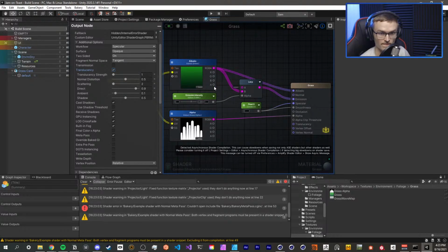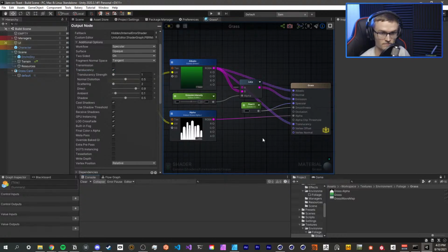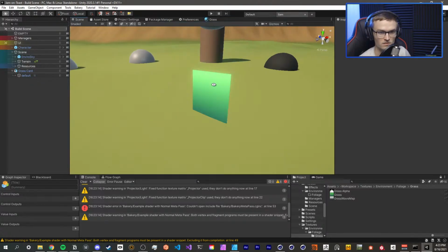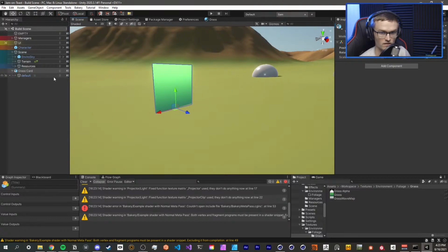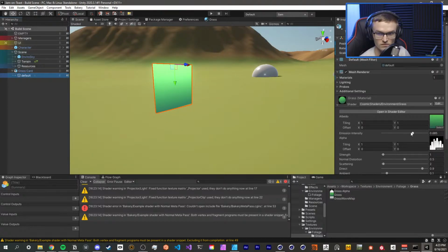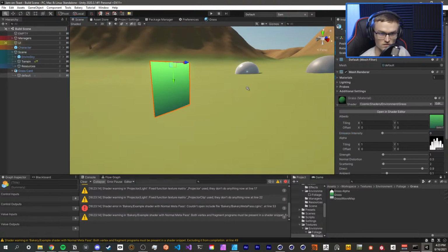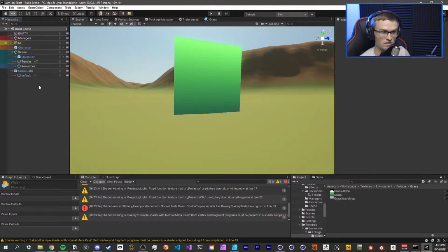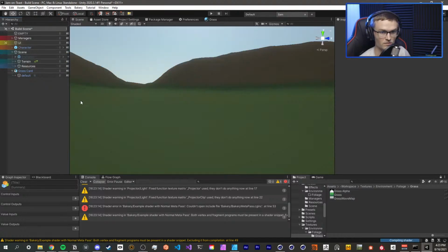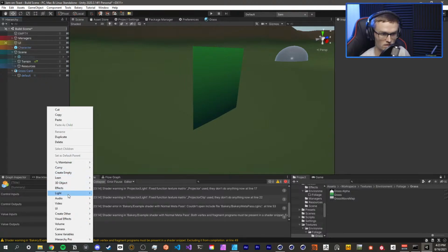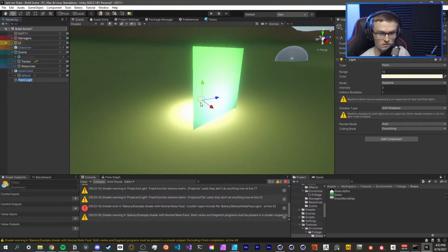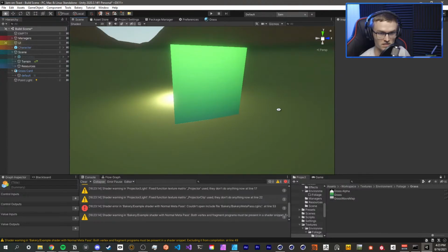Let's drop that color in there and see how that looks in the back. Even if we don't get shadows working right now, that's okay. We'll get them working later. Let's turn the emission off and see what it looks like from behind with translucency. Also, let's turn off the sky environment and drop a light in. Point light. So we can see what the translucency looks like.